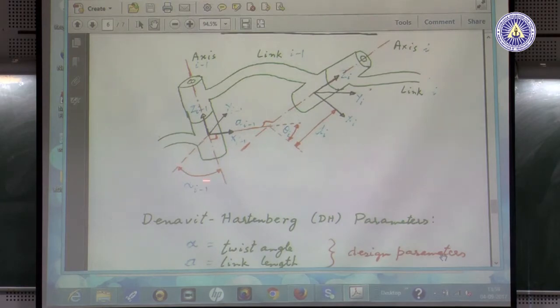It has been shown on the back side because on that side there was not enough space. So, by that alpha i minus 1 you turn this frame about the z axis, so that this x turns and comes like this and becomes parallel to that. Then as x turns, y also will turn; x will become parallel to this, y will become somewhere, something you do not know.